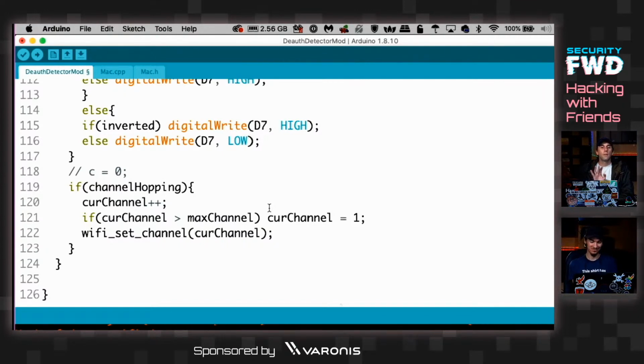So in this code, if I turn on the light and wanted to delay for a certain amount of time and then turn off the light, this code would crash. The reason is the Wi-Fi radio needs to use the clock, and if you halt execution for like 10 seconds, the code freaks out and it dies. So it's very hard to put delays into code like this.